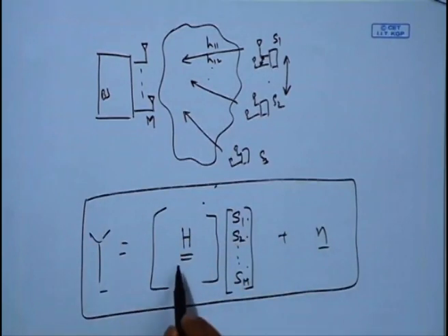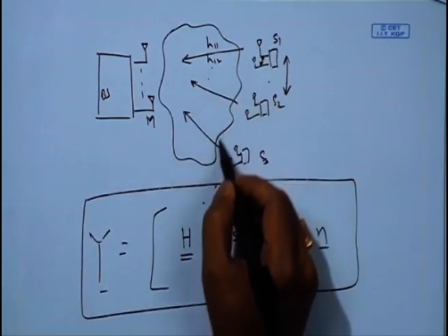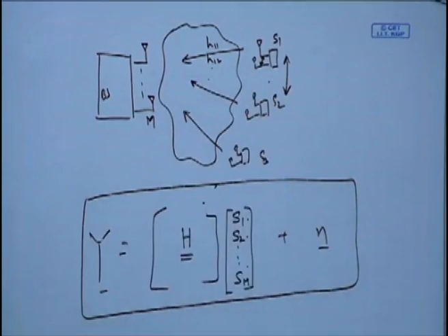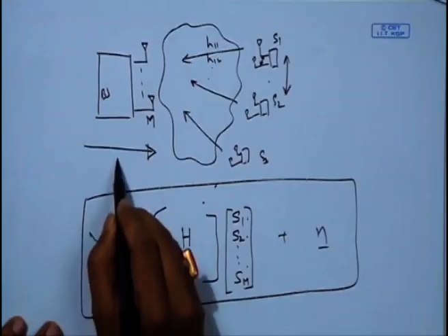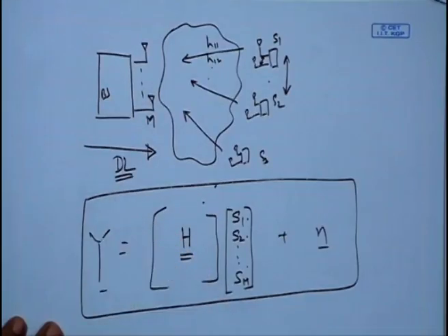If the channel is orthogonal, that means it may be possible that channels are orthogonal because users are separated by far distance, one could usually use a matched filter receiver. With a matched filter, if it is orthogonal, one could still identify the received signals. Otherwise, one could use a channel inversion if it is an invertible channel, or one could use successive interference cancellation and proceed.